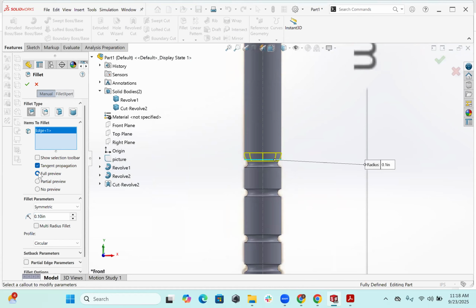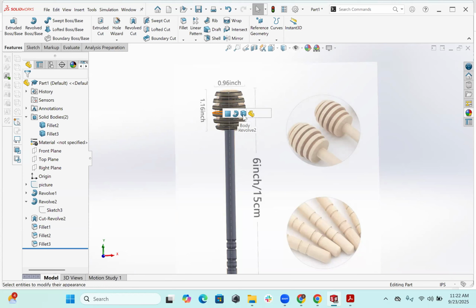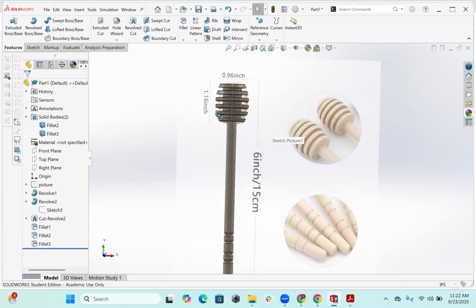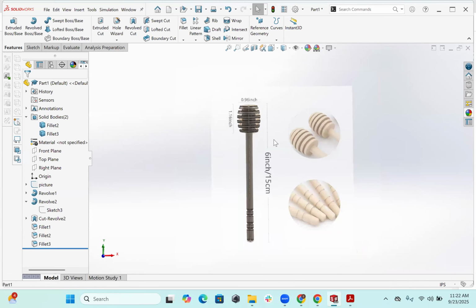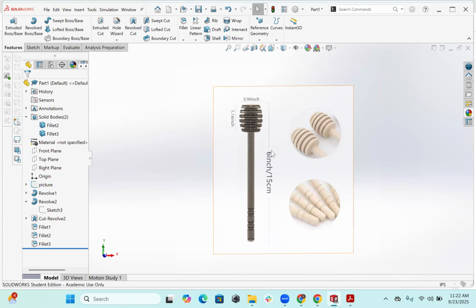And reach maybe. So I can drop this. It asks me if I want to drop it on the face, on the feature, or on the body. So I'm just gonna put it, or on the part. I'm actually gonna put it on the whole part. We usually don't add appearances. We're gonna go to Keyshot to learn to do that, but this is just to visually separate parts, you could add color.